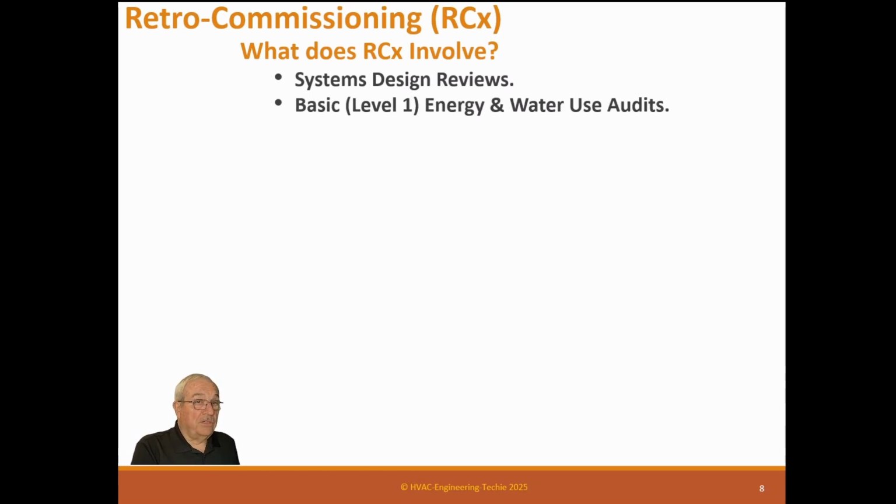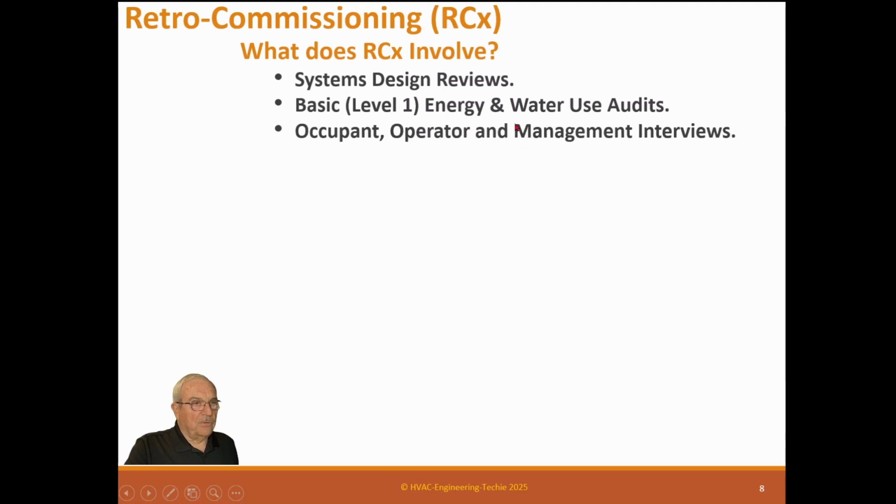Basic level 1 energy and water use audits. That's included in a retrocommissioning project, but it's much, much more than that. It's only level 1. We'll explain this later in the other videos, but level 1 is basically just figuring out how much energy you're using and whether it is good or bad. It doesn't tell you a whole bunch of details after that. And we need to do energy and water. We have a lot of guidelines from ASHRAE on exactly how to do an energy audit. Not many on how to do a water audit, but we'll go through that. You can use the same criteria they have at ASHRAE for energy, just apply it to water.